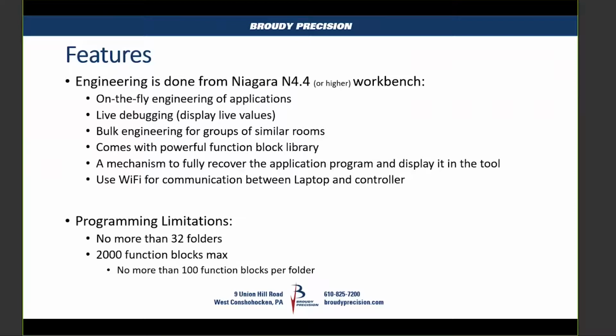There's no folders, there's no naming, unless it's the BACnet controller and it's just the I/O. You'll see the BACnet names come through. But when you bring that in, it'll bring the whole application in. And then there is an adapter coming out to be able to do Wi-Fi communications. It's basically a BACnet Wi-Fi device, but that's a future thing.